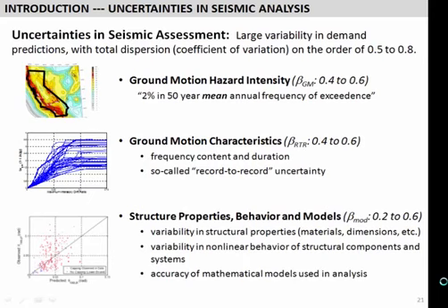So think of that as you're building your model, choosing your software. Now I did want to bring up, you see in those slides that I just showed, there's variability in our output. One of the things in doing these nonlinear dynamic analyses, it's unsettling because it looks like there's more uncertainty in our designs than there ever was. But the fact is that uncertainty has always been there. You can think about, we're checking things at MCE level ground motions, let's say. There's uncertainties in even how we define that MCE. When you look at the hazard functions, they're mean annual frequencies. So there's uncertainty about that mean of just what the MCE level intensity of ground shaking is.